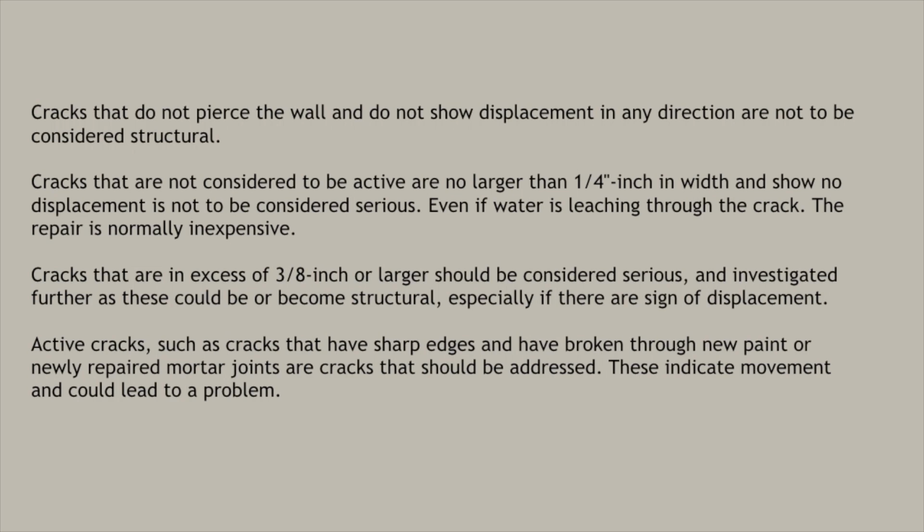Cracks that do not pierce the wall and do not show displacement in any direction are not to be considered structural. Cracks that are not considered to be active are no larger than 1/4 inch in width and show no displacement, and are not to be considered serious. Even if water is leaching through the crack, the repair is normally inexpensive.